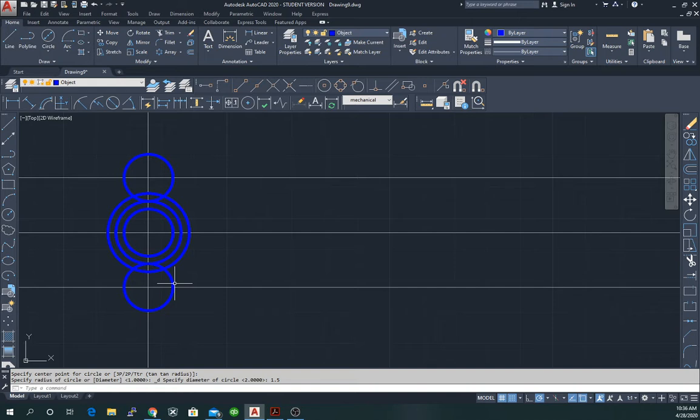Now, what is a counter bore? A counter bore is a hole that's essentially made with a drill bit with a flat bottom. So the flat bottom essentially drills down and makes a hole that goes down, in this case, 1/8 of an inch, but the bottom is flat.